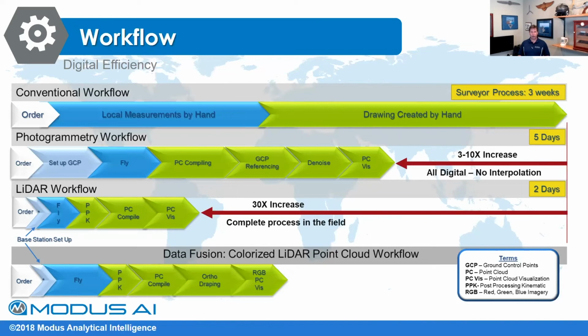Now, what we're going to add on to that example is what I see on a typical day when I'm using LiDAR. And I've been very conservative with the numbers that I deal with. But typically, let's say I'm doing 15 acres. A really good example I did a couple months ago was a rock quarry. I was using just a VLP-16 and a DJI 16 drone. I cleared 15 acres in 22 minutes.